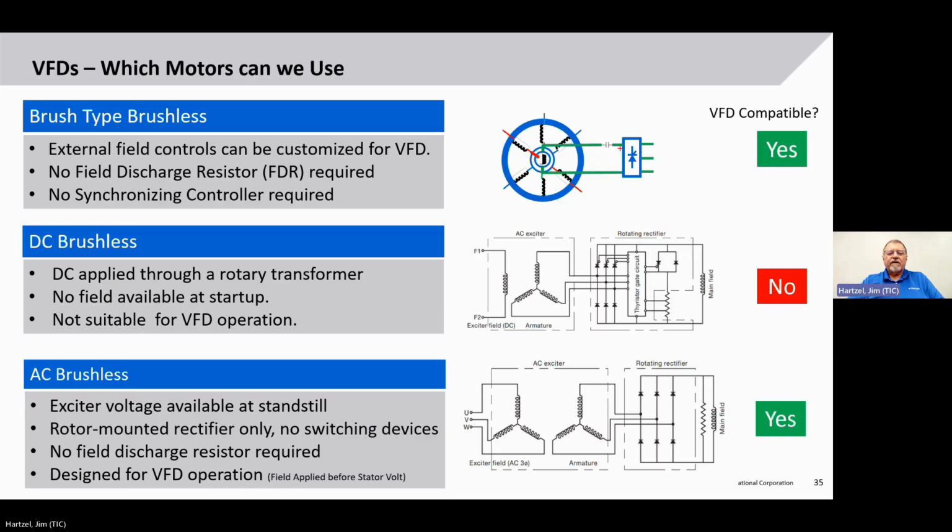So I get requests all the time that say, I have a brushless synchronous motor, can you supply me a drive? Well, that depends. Is it a DC brushless or is it an AC brushless? There's an important distinction there.